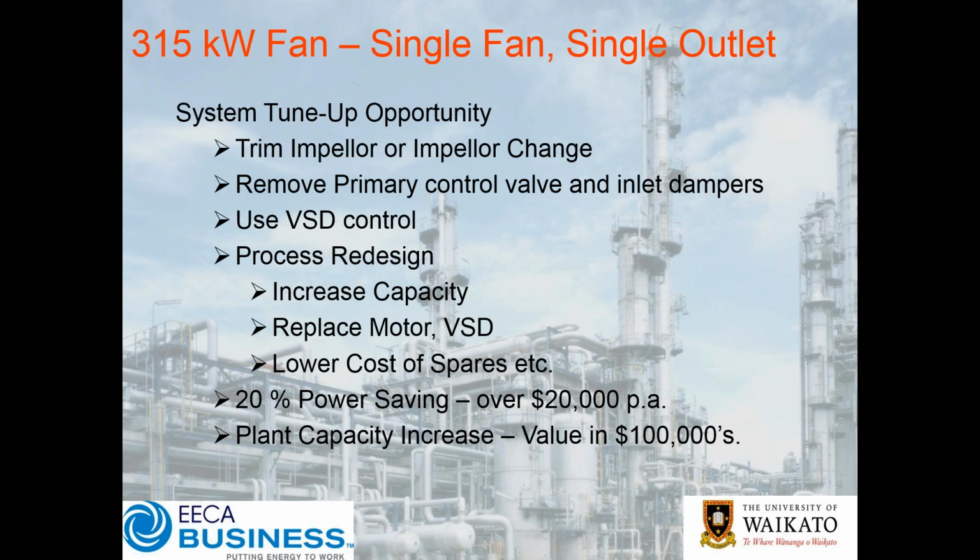But in real simple terms, typically a minor trim, you'll literally just take a little bit off the existing impeller. If it's a little bit more substantial, then it might be just a straight impeller replacement. That can be done relatively quickly. Often that's less than a one-day shut if everything's all prepared in advance.